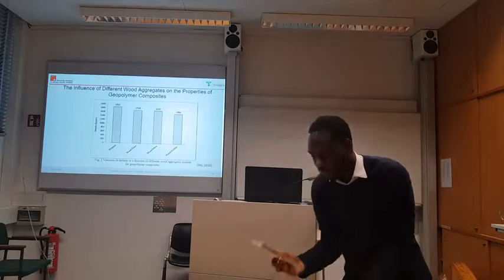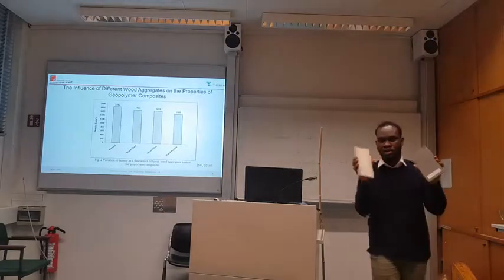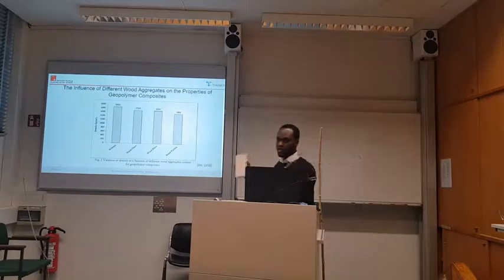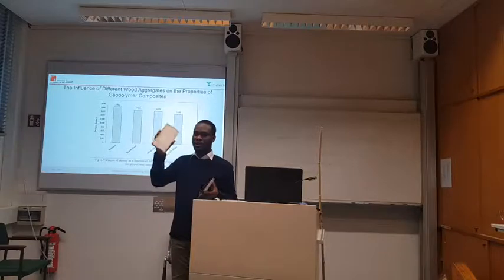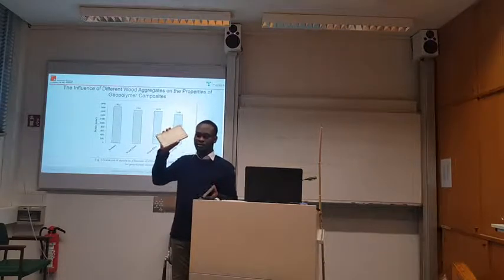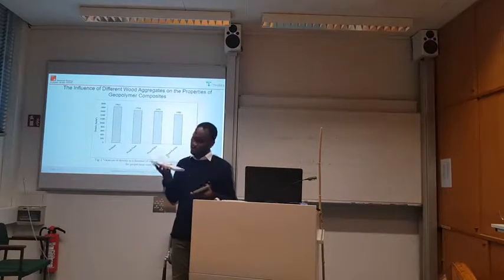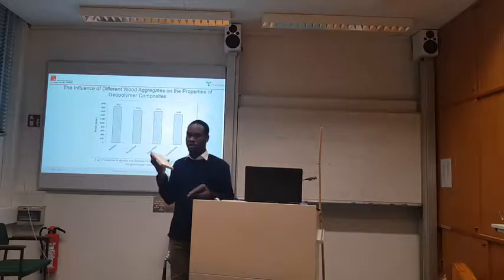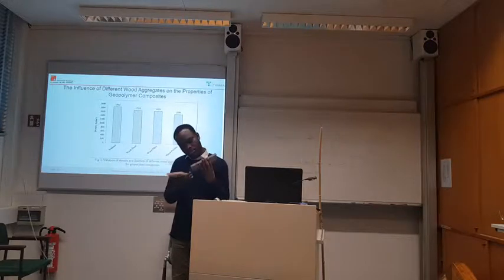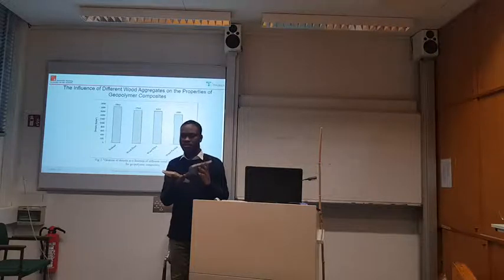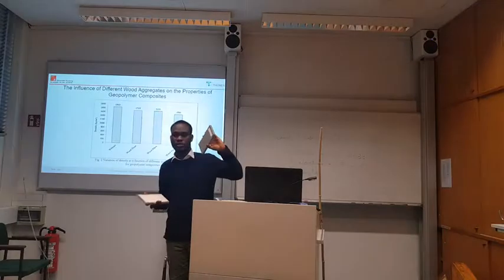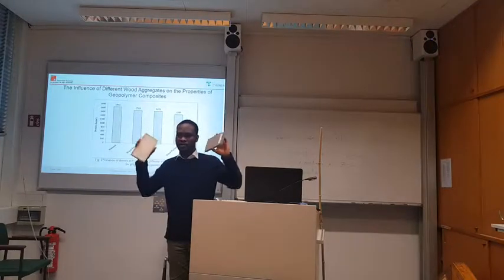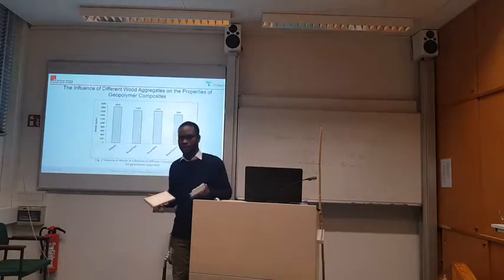So these were produced also here using our laboratory technology. We have this geopolymer from metakaolin, and it's a board with 50% spruce, and this one is from fly ash from coal, and it's also 15% spruce. But the density is totally different because of the starting material.